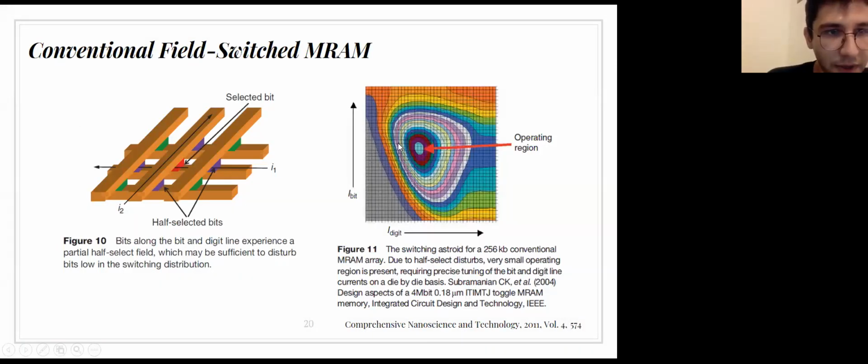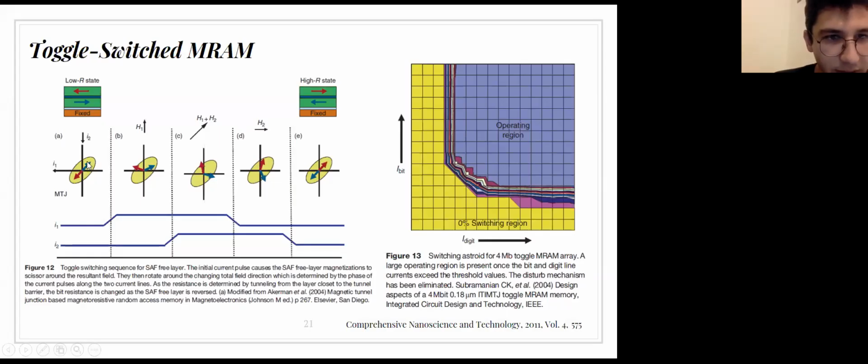So, fixed layers, we see anti-parallel alignment here. When we give the first current, we see that we change the orientation by 45 degrees, which provides a stable orientation. So it's more difficult for fluctuations to cause any changes in the overall orientation. Here we go, we apply the second axis too. We have both at 45 degrees.